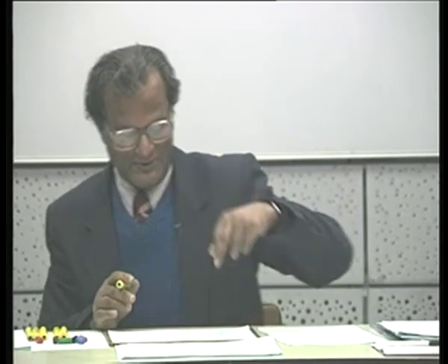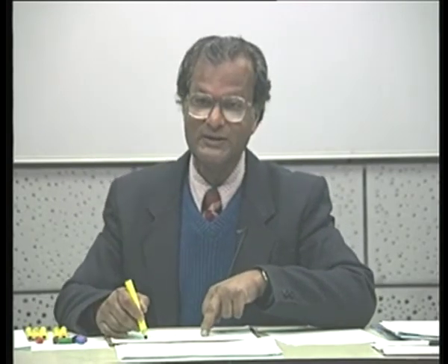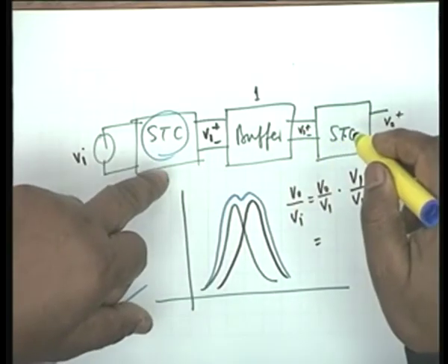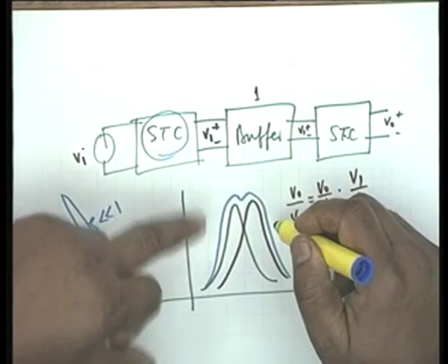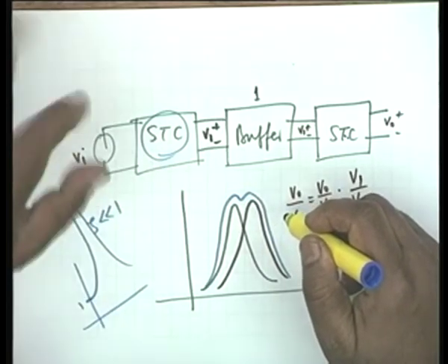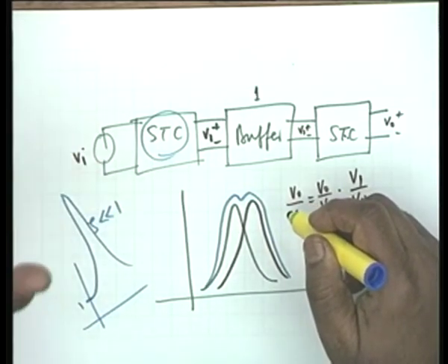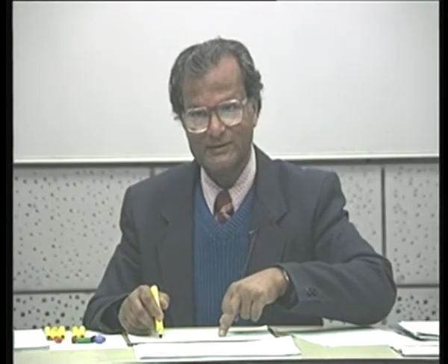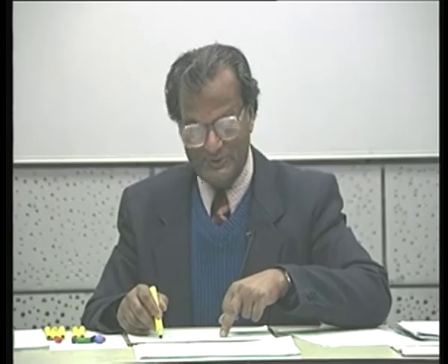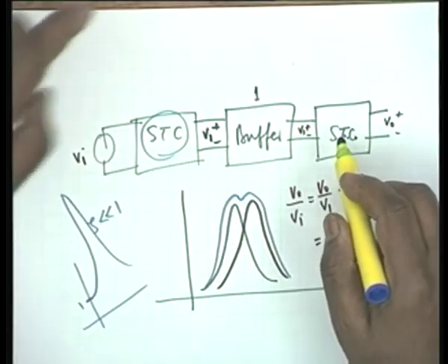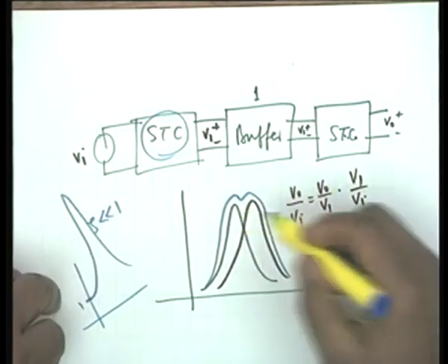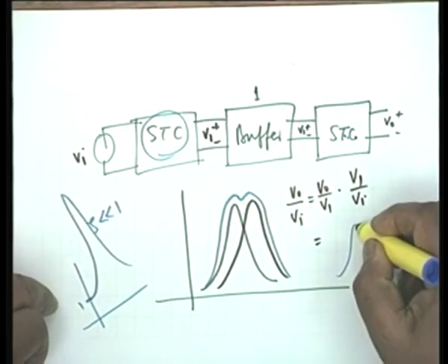Alright. What I am talking about is two single tuned circuits being coupled and decoupled like this. They will produce a response which is similar to the response of a double tuned circuit. Alright, now what is your question? These are not double tuned circuits. If both of them are double tuned circuits with slightly different tuning, yes, that's right, then I shall have a response like this.